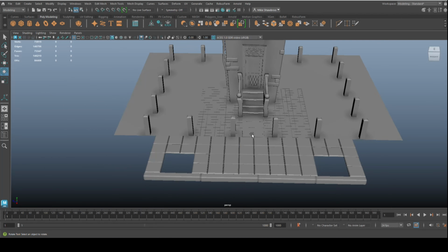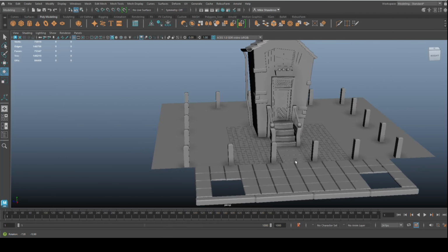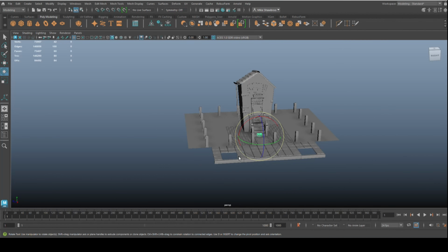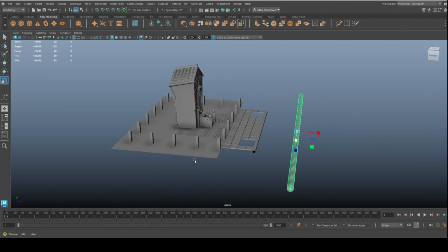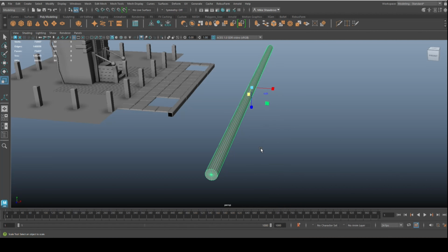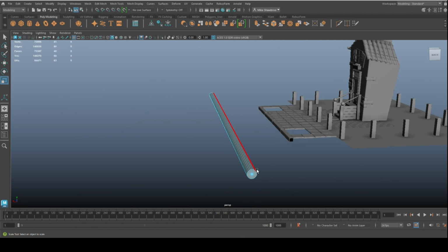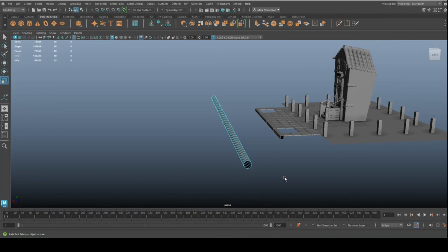Now let's get something in here to make this look more like a fence, right? So we're just going to simply take a polygon cylinder. We're going to hit E to rotate, hold on J, flip it on its side. And the guinea pigs agree, looks like. Delete that. Hold down the tab key. Delete that.